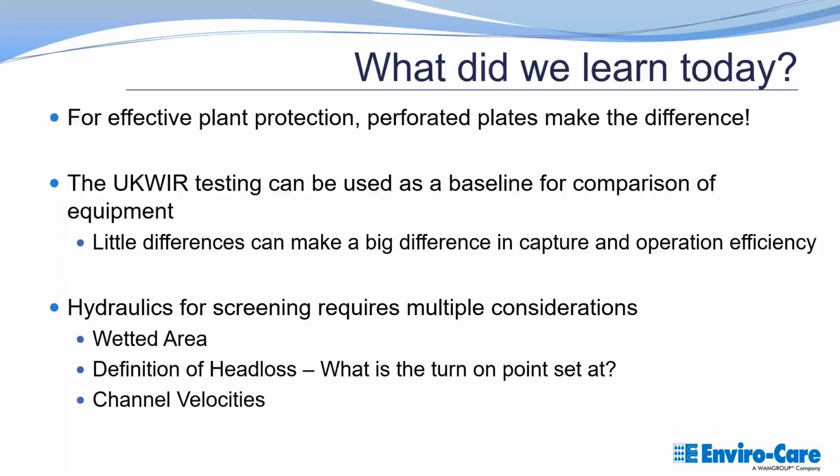And then, of course, hydraulics. Screen design is not simple. It requires a lot of different considerations when you're looking at how to best operate that screen. That includes your wetted area, getting into that head loss, what is the head loss, what is allowable, and ultimately, how frequently do you want that screen to run? And then your channel velocities. You want to make sure your channels themselves are working properly.